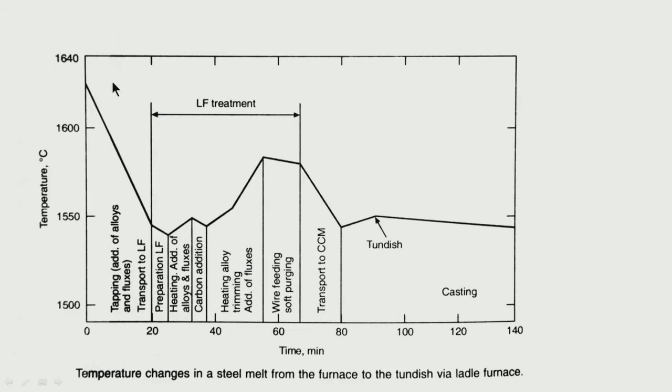In the process, the extent of dephosphorization is relatively less if you have a higher temperature here. So now, what is going to happen? We are tapping it and adding the alloying elements. All these will cause the temperature to come down by maybe about 70-80 degrees centigrade.